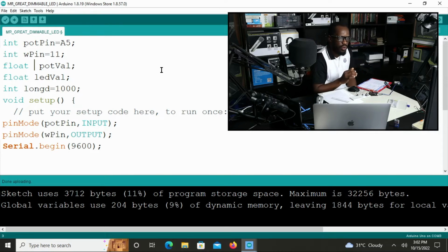So you use these pins for all your analog projects. And when you want to read an analog voltage from a sensor, not digital, you read from analog pins A0 to A5. So we are using A0 to A5, and I choose A5 because I want to use A5. And I choose pin number 11 that has the wiggling sign because I want to use it. You can make your choice and choose any of these pins, and you can also write with it. Okay, so let's go to the IDE, which is displaying on your screen.